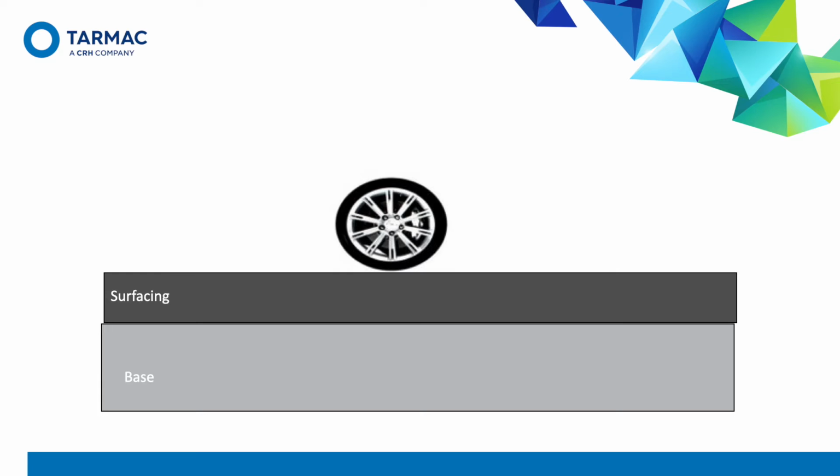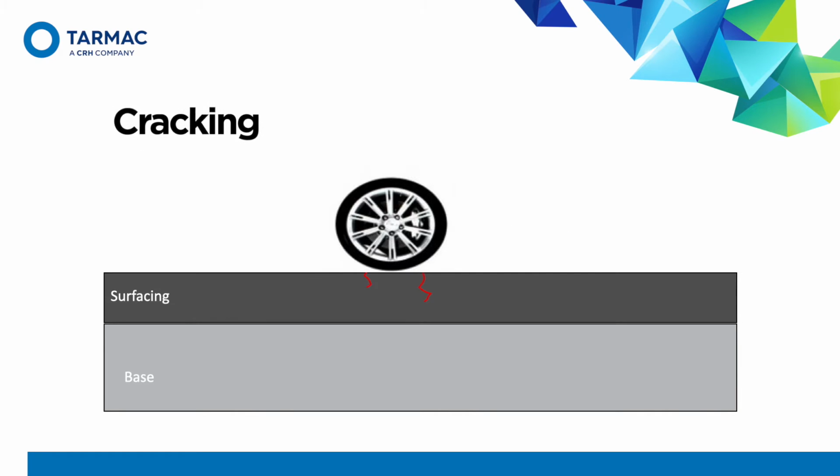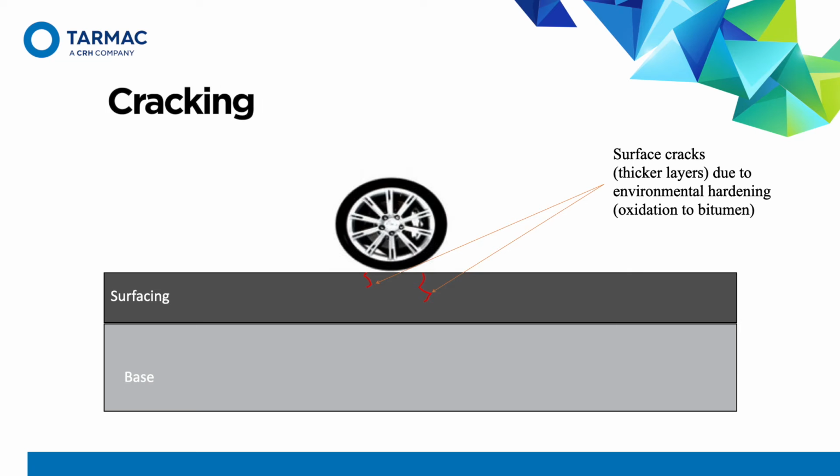So how does the asphalt mixture or the road pavement fail? Road pavement does not last forever, but gradually deteriorates. The most common pavement deterioration mechanisms are cracking and permanent deformation, or rutting. Cracking, which can appear on the top, usually appears on thick pavements due to the environmental hardening known as oxidation of the bitumen on the surface. This type of cracking, from the top to the bottom, is known as top-down cracking.